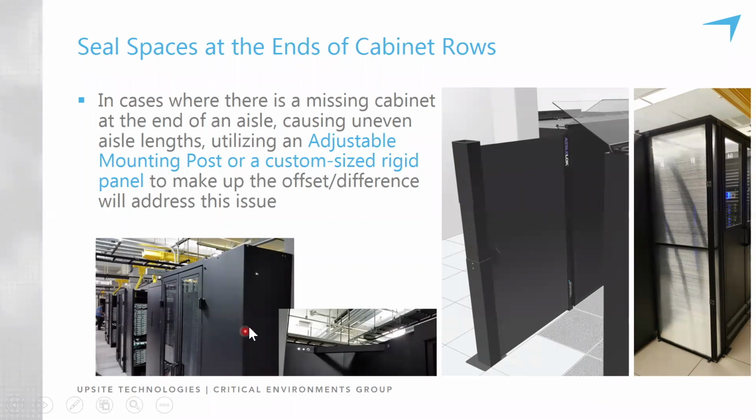You can't see the building column, but it's another one of those big white columns you saw in the previous slide. So we designed a steel enclosure to span the rest of the aisle and return back to the column. And then inside in the insert where you've got the 90-degree angle, there's a brace in there so that when these doors close, it doesn't wobble or shake, and it adds to the structural integrity.